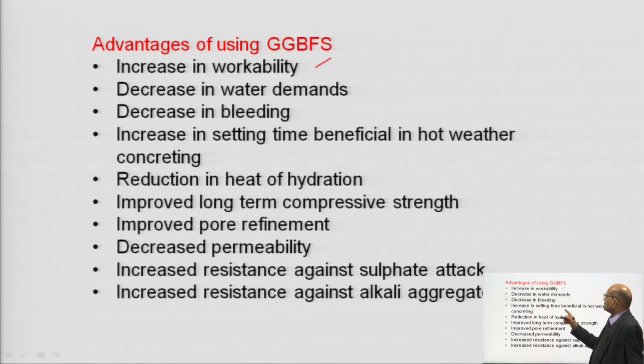Then this gives you a decrease in water demand. If you consider the water requirement, it is reducing here. So, the water cement ratio will reduce for the same workability. Okay. So, water demand is reduced.